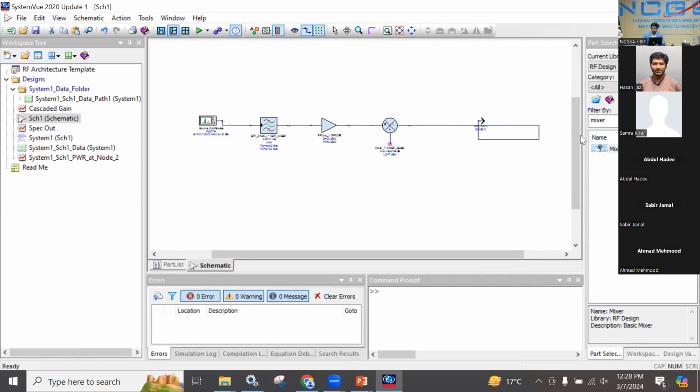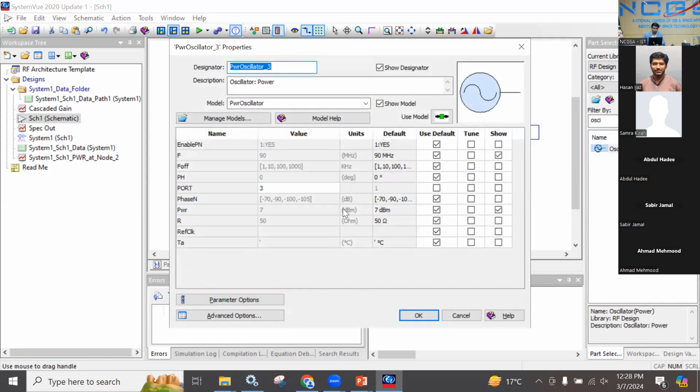And this is a frequency mixer, you need an LO source as well. So we may have an oscillator as well that will drive this mixer. Since the input frequency is 5 gigahertz and the IF, maybe we can have 500 megahertz. So the LO frequency I will enable as maybe 4500 megahertz. LO power we will have 13 dBm, for instance.